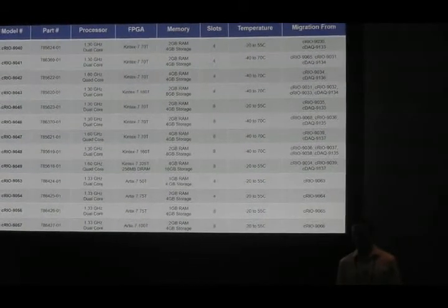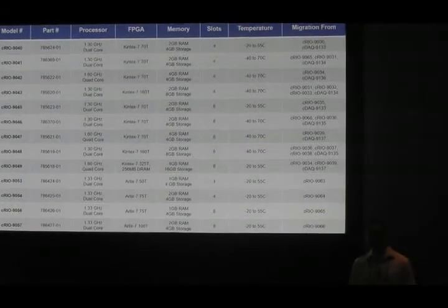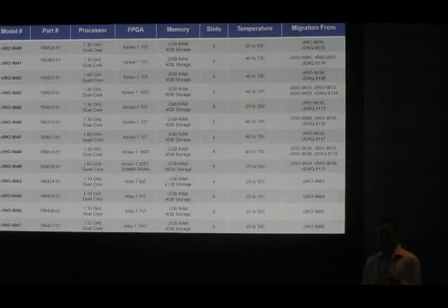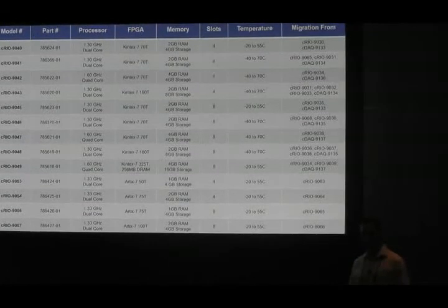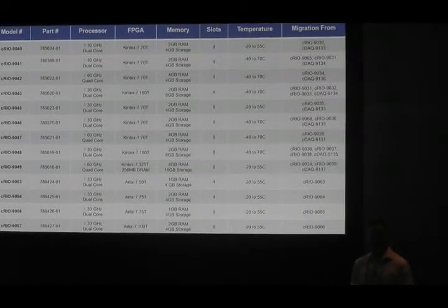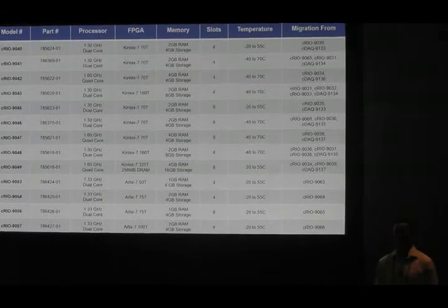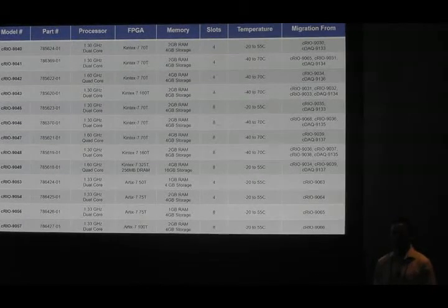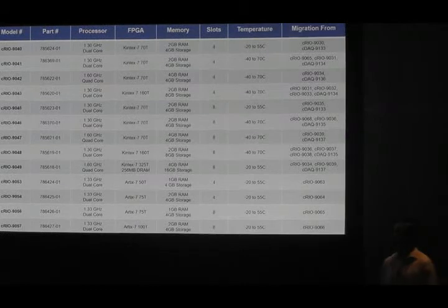And usually they don't need as big of an FPGA to do that intense processing on the CPU. So what we did was we decreased the FPGA size, increased the processor to a quad core, and integrated that into one product that's now rated for -40 to 70C. So you now have a new processing performance point in terms of variants in this product. This one we're pretty excited about, and we think will be pretty interesting, especially to a lot of those deploying around heavy machinery or remote systems that are deployed outside.